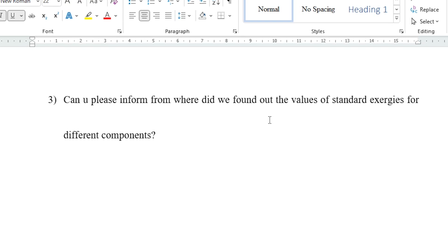A table will come. Obviously, I can't share it over here due to some reasons, but it can be easily taken from the literature. Currently the chemical exergy calculations are not incorporated in Aspen. What we get by specifying the reference conditions are the physical exergy values, and then we go to Excel, we apply the formulas over there and we can get the values of chemical exergy.